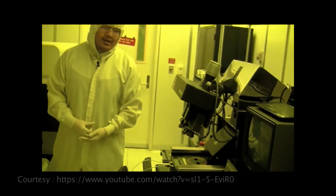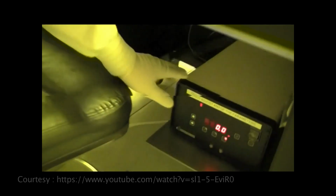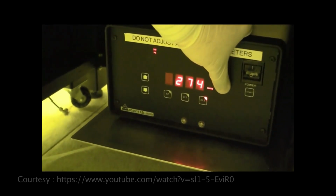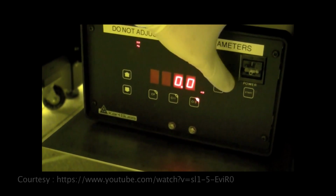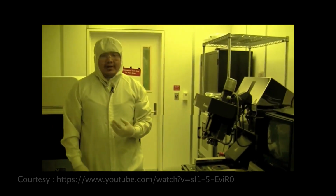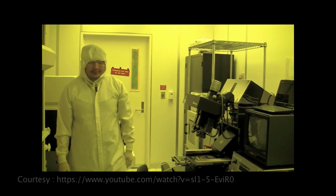But in addition to that, you want to find out how many hours are left on the light bulb. So you check the power supply. You hold this button called DS. And it says 3226. That's how many hours the bulb has been used. The bulb has a lifespan of 4,000 hours. So when it's over 3,500, you would notify staff and tell them to change it. So we're pretty close to that.